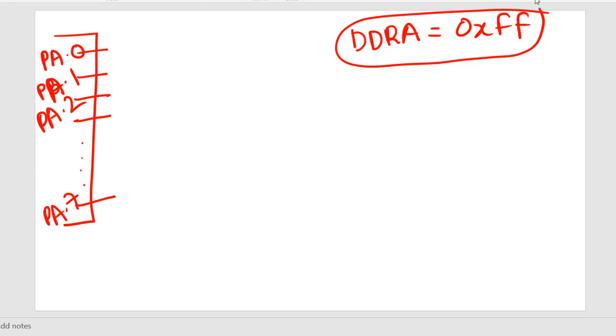So whenever you are sending data to a particular pin, you have to send 1 from your code. When I am sending 1, that means a high bit. You have already completed your digital electronics course. You know that there are high bits and low bits. High bit means 1 and low bit means 0. So whenever you are writing a 1 or a high bit to a particular port, what will happen to this port? When you are sending 1 to a particular pin, or 2 pins or 3 pins, you are supplying 5 volt to a particular pin.